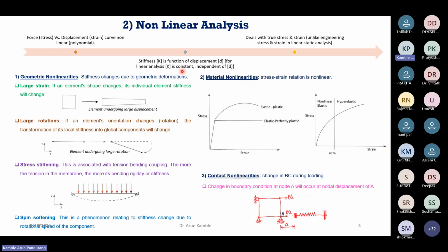In general, in engineering, or in finite element analysis, we analyze only three types of non-linearities. First one is the geometric non-linearities. So what are the geometric non-linearities? Here, the stiffness changes due to the geometric deformations.